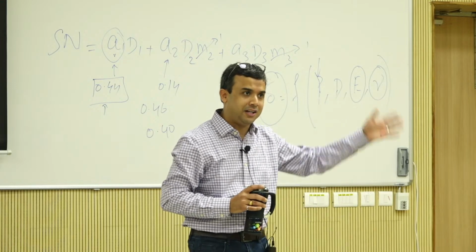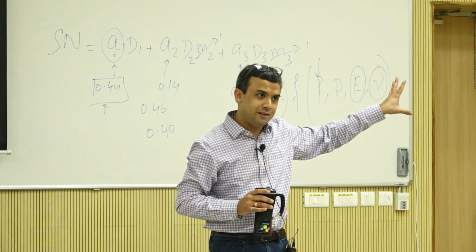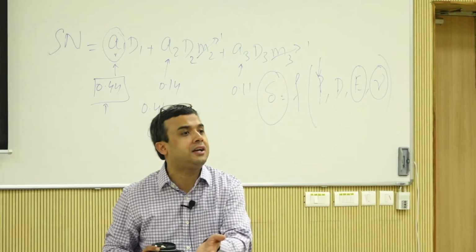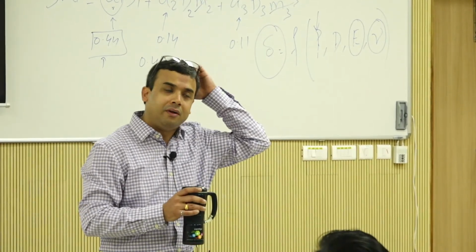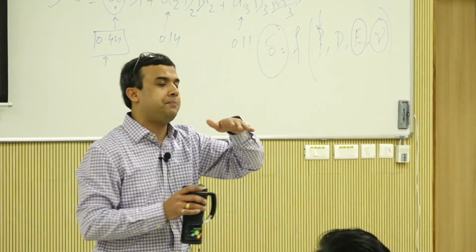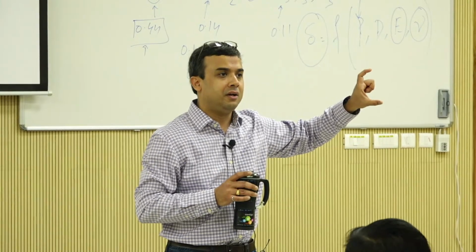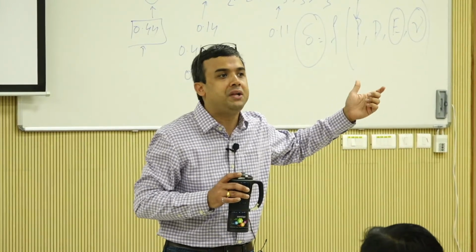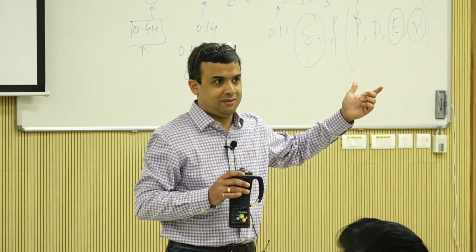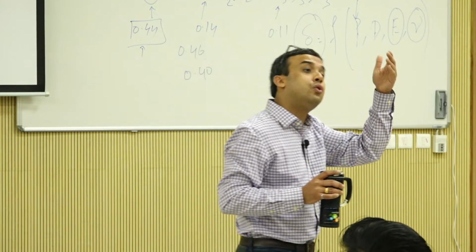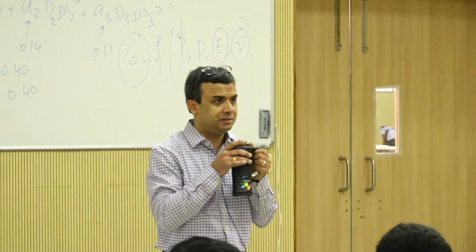Nobody has run all the tests. So that data is missing. And the data is not just missing, it's constructed data. Some of you, I'm sure, are familiar with construction practices. You specify 50 millimeters. The actual construction is sometimes 45 millimeters, 52 millimeters. It all depends, right? So that is going to change your response of the pavement. So that's what back calculation is.